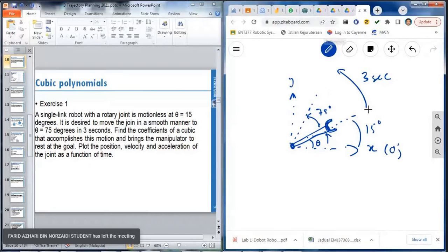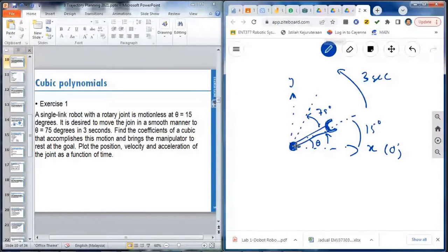You want to make sure that your motor does not start rotating immediately. We call that abrupt starting. So you need to control your velocity from slow until high speed, and then from high speed you want to stop, but not immediately.